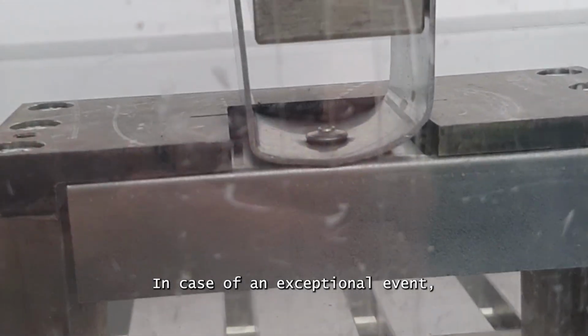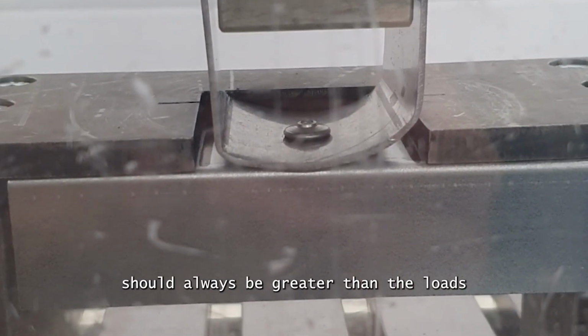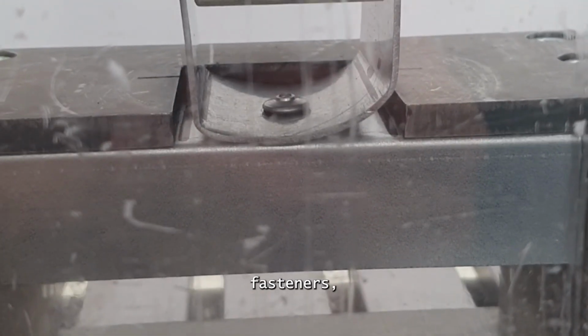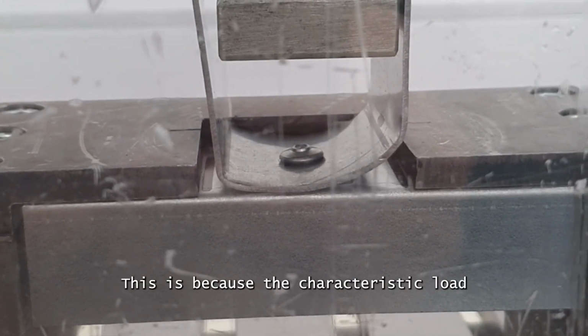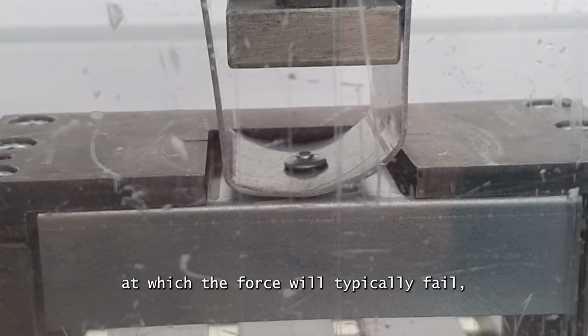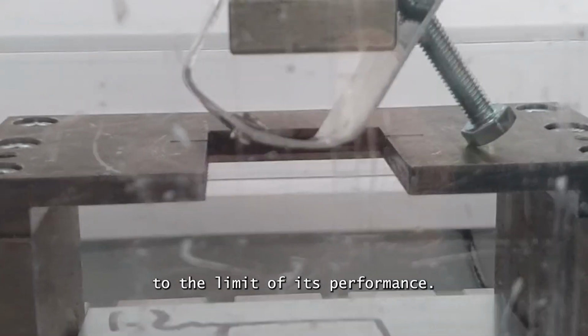Which load value should I use when specifying fasteners? The strength of a component should always be greater than the loads applied to that component. When specifying fasteners, you should use the design load, not the characteristic value. This is because the characteristic load is the value at which the fastener will typically fail, whereas the design load includes the safety factor to ensure that the fastener will not be taken to the limit of its performance.